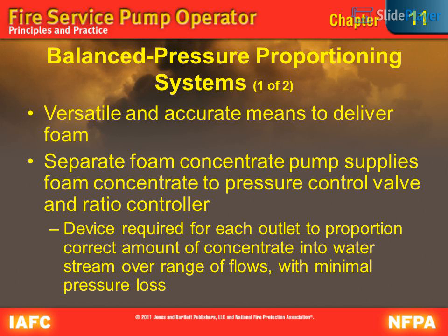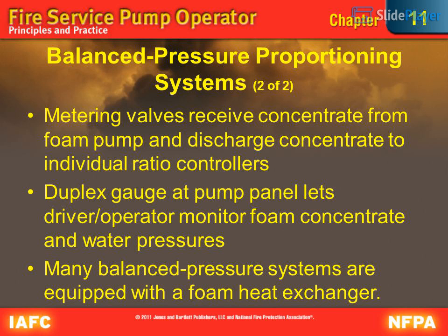Versatile and accurate means to deliver foam. Separate foam concentrate pump supplies foam concentrate to pressure control valve and ratio controller. Device required for each outlet to proportion correct amount of concentrate into water stream over range of flows, with minimal pressure loss. Balanced pressure proportioning systems, 2 of 2.